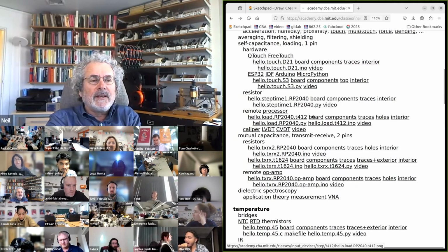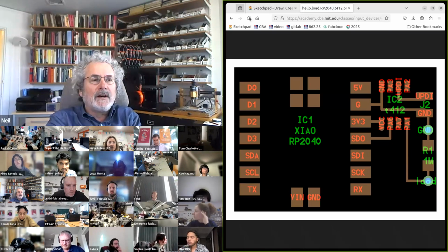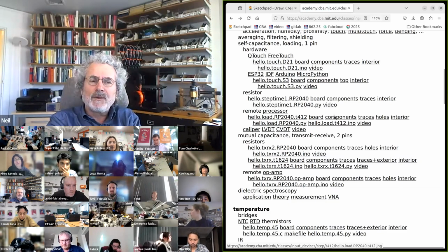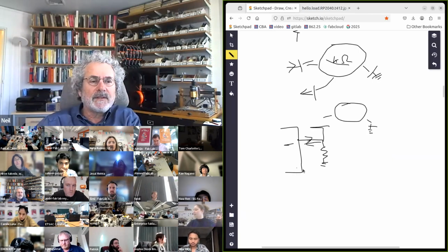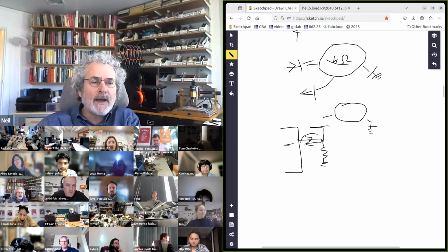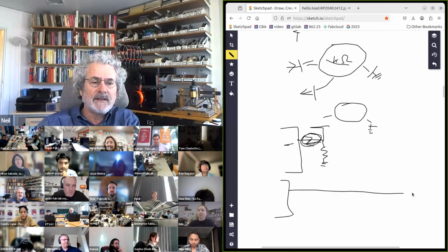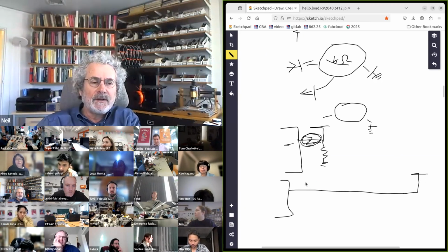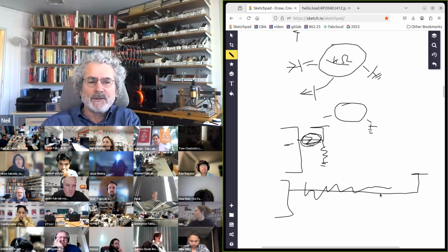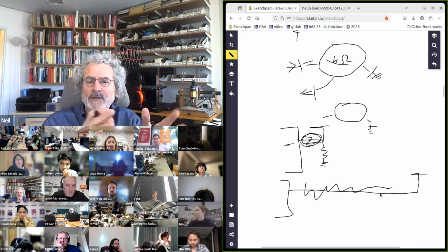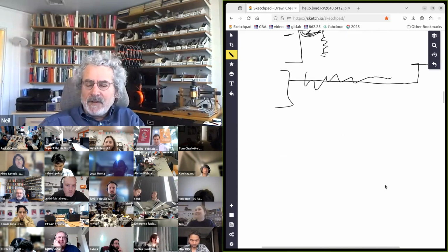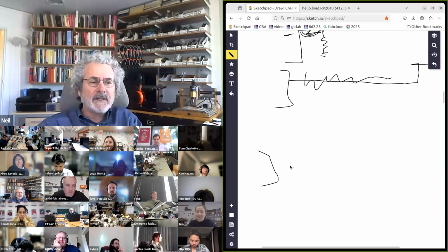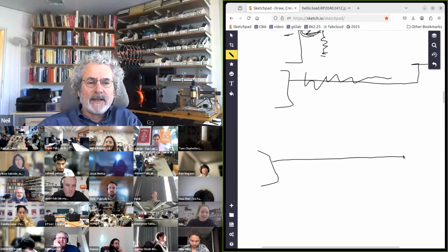Now, this next version, I'm going to add a processor. And so here's why I'm doing that. When you make this measurement, this wire is sensitive. So if the processor's here, but the electrode is over here, you're going to be measuring everywhere the wire goes. And if you touch the wire, or if it goes near something else, you'll get noise, you'll get interference.